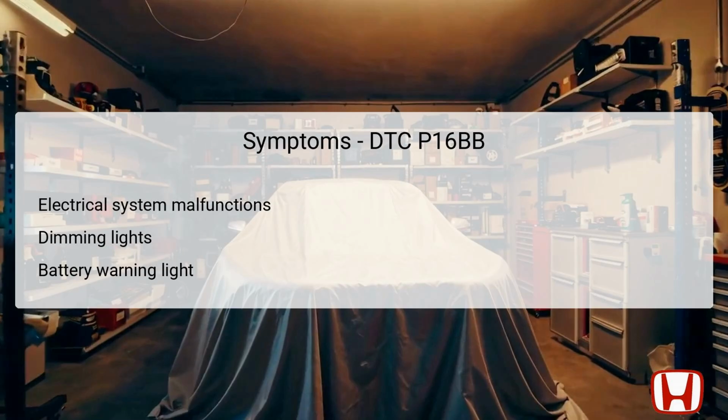When experiencing the DTC P16BB, several symptoms could manifest as a result of the low voltage condition. Users may notice electrical system malfunctions, which can range from malfunctioning interior lights to unresponsive electronic features. Dimming headlights is a common indicator, as insufficient voltage directly influences the ability of lights and other accessories to operate correctly. Moreover, the vehicle may illuminate warning indicators on the dashboard, particularly the battery warning light, suggesting that there are issues with the charging system.